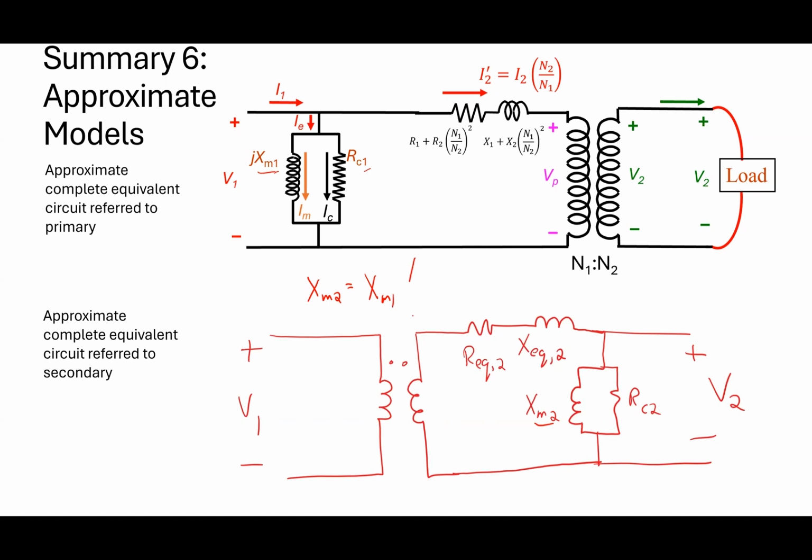So I multiply like that, right, by the turns ratio. Similarly, if I give you the parameters on the secondary side, you reflect them over through the opposite of that. So this ratio squared, does it work for everything that we want to reflect over? So all you do is take the turns ratio squared? You've got to remember which way to apply the turns ratio squared. Is it N2 over N1 or is it N1 over N2? That's basically the deal.